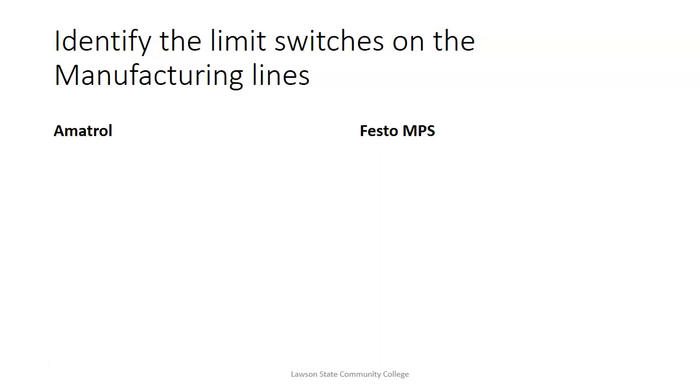Not when you're only troubleshooting, but when you're actually working on something, right? Normally when we troubleshoot, we don't lock out, tag out, because we've got to see the thing operate. We're going to have to take voltage measurements and that kind of stuff. But when you get in there and start replacing parts, that's when you need to lock out, tag out all power sources, right?